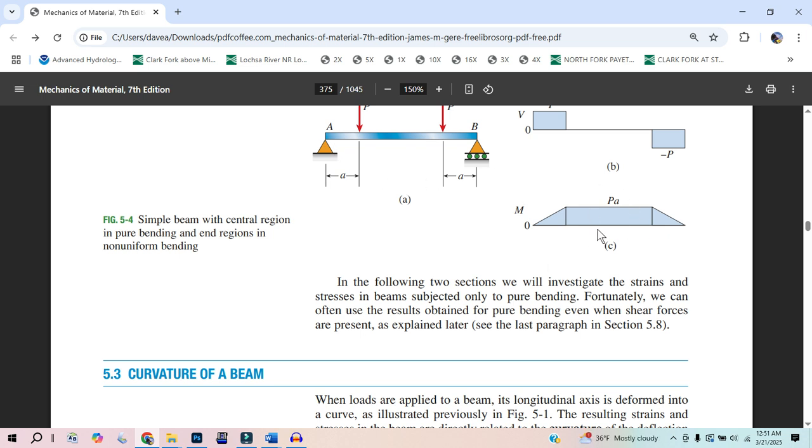And so here, yeah, we can just use this max number for our moment, and we can also find the other stresses in parts of the beam. You don't have to just find the max stress, but if you're going to throw an I-beam across a 40-foot span and drive your car across it, well, that's the only number you're actually concerned about, that max number.